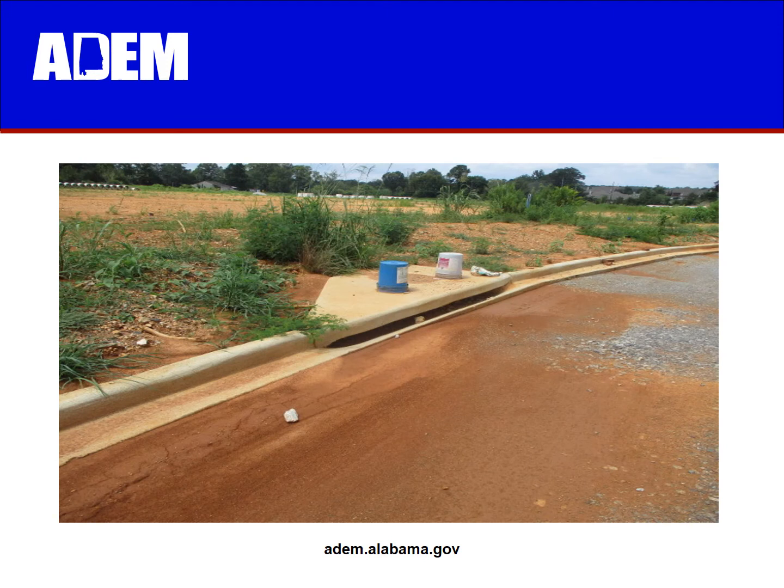A lack of proper BMP installation at curb inlets can allow large quantities of soil to be deposited off-site or to be deposited in the sediment basin, which results in increased maintenance costs for the sediment basin.